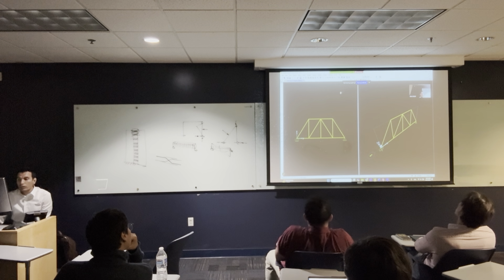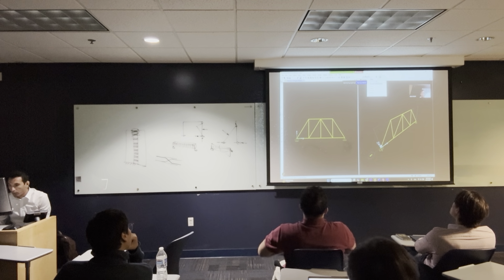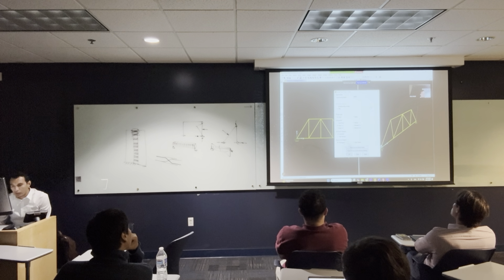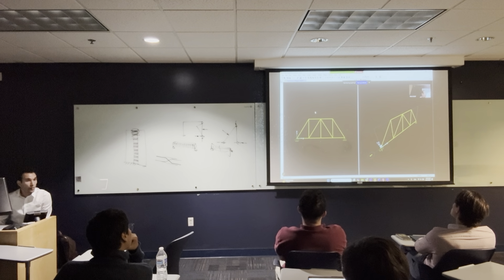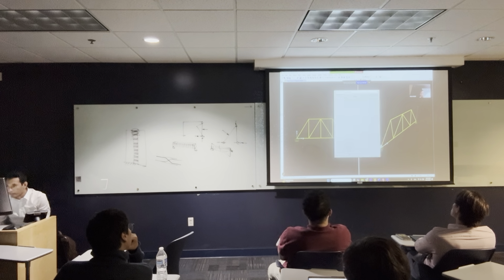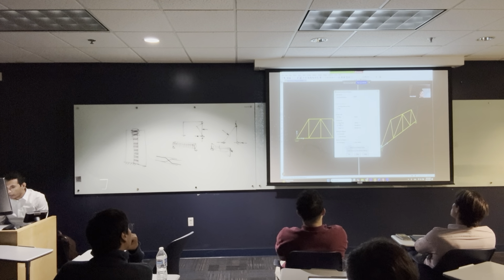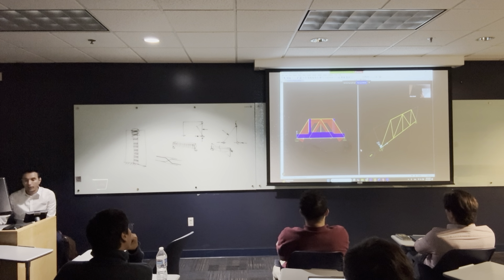Okay, so if you want to show the shear force, you can come here and show frame and cables and show the shear 2-2. And the shear 2-2 also is going to be 0. There is no shear. Only there is axial force. So I'm going to show an axial force, and then I'm going to hit OK. And this is the axial force that we have.